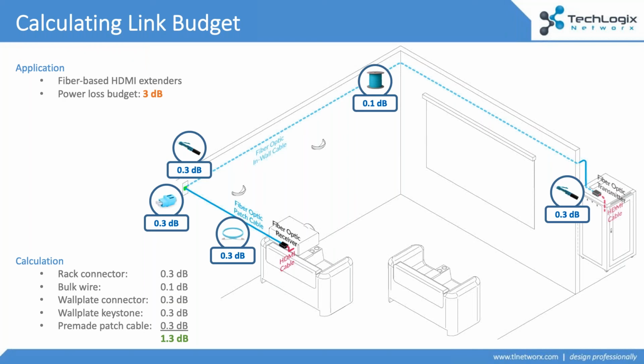Now, when we get to the next part of this dialogue, taking your actual meters, if you have meters, and plugging them into the cable to see what your actual loss is. And if you find out it's more than 1.3 dB, now we need to start thinking about troubleshooting.